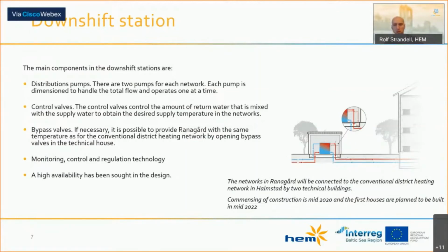And each pump is dimensioned to handle the total flow. So we are backed up because this is a very important part of the network. We can't have the system going down while servicing one of the pumps. And we have control valves to control the water mix, so we get the desired temperatures.